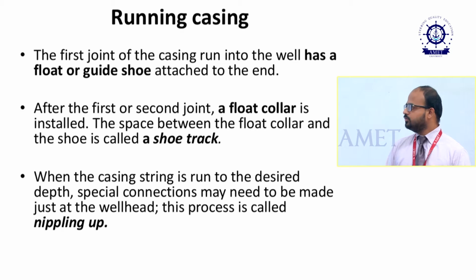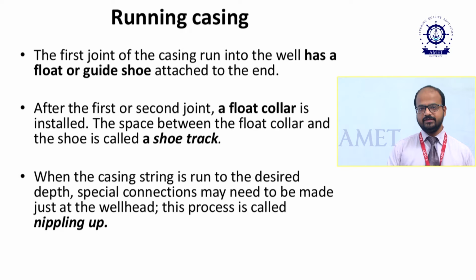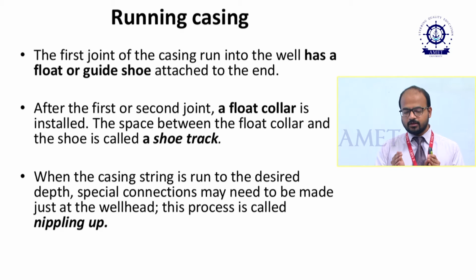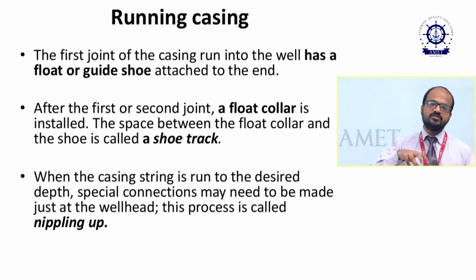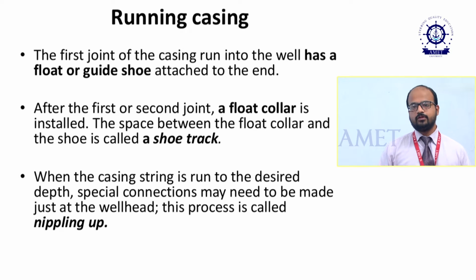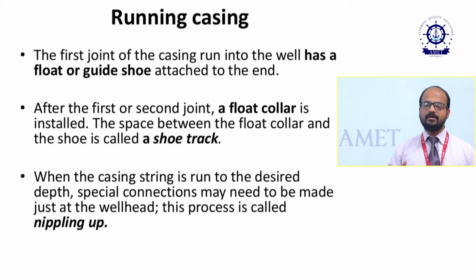Once the floating shoe is entered, the structure at the bottom, for a few feet, is thicker, and the shape at the bottom is spherical. Why is it like that? Because we have to make another thread with another casing further. If I say 8,000 or 9,000 feet, you have to connect at least 60 or 70, 80 casing pipes that we have to insert.